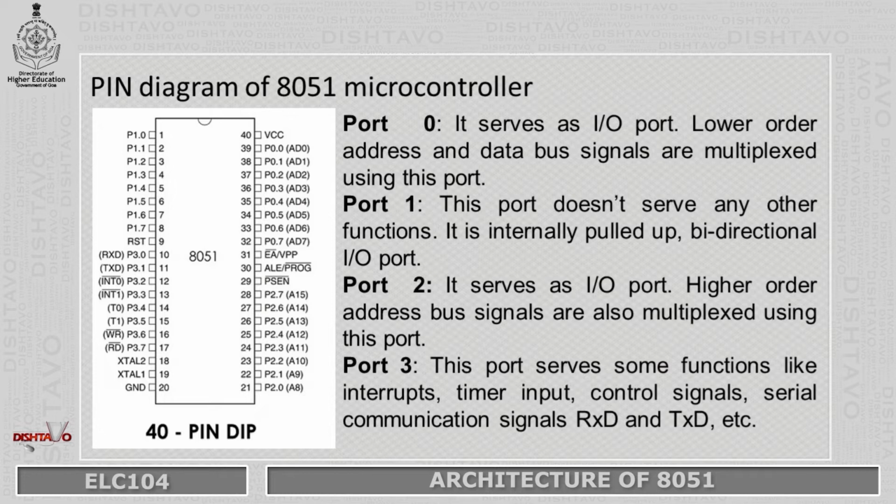Generic 8051 microcontroller is a 40-pin dual inline package type of a device. So there are basically 40 pins, and out of 40 pins, if you go to see, 4 ports are occupying 32 pins, then 2 supply and grounds are there. Then we have 2 pins for crystal oscillator, and then we have 2 pins meant for external access / VPP, and 1 pin for ALE, 1 pin for PSEN bar, that is program store enable.